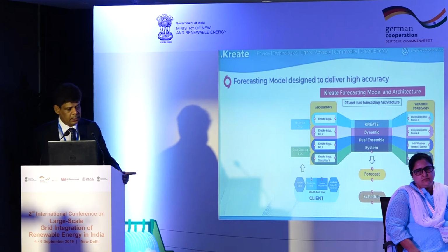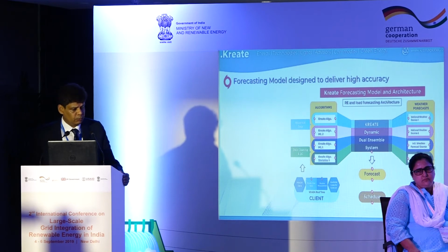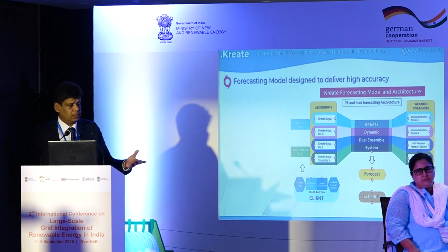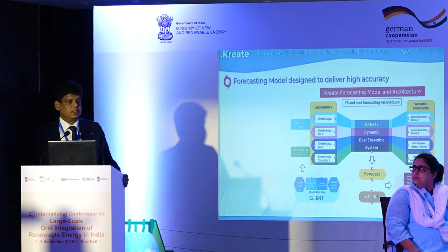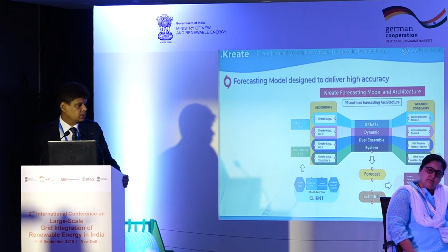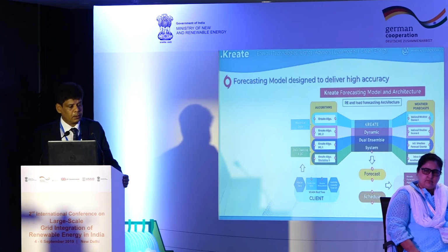And these are all, as I said, for demand. You can create a real-time forecast anytime, because on the screen a user, which could be an SLDC or an RLDC, can create a real-time forecast as on the data available right now. But typically what we provide is a day-ahead forecast to SLDC, and for generation, it's a combination of day-ahead as well as intraday, based on the number of revisions currently permitted. And on a regular basis, the errors which come up are analyzed and incorporated into the model.